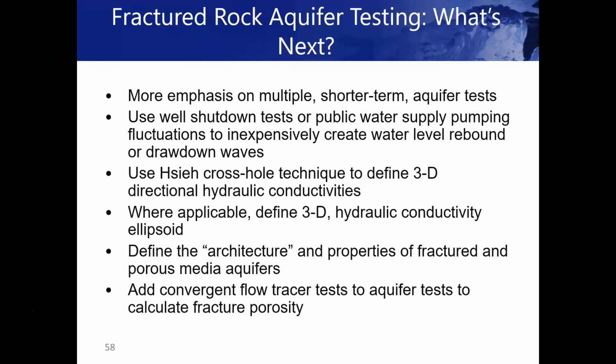So that is a factor if that's something that you may be dealing with. And that may be a reason why you could want a longer test. Most of the water supply aquifer tests are going to be a minimum of 24 hours and more likely 72 hours or more, just by regulation. But if you're working on a contaminant site and you need to get a lot of information about hydraulic conductivity and storativity, then I think there's an opportunity to do shorter term tests.